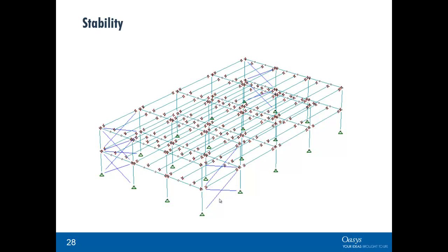Similarly, the steel frame as a whole: the real steel frame will have a concrete floor in there, which acts as a diaphragm. The model without that is maybe stable around the brace bays, but elsewhere from that, it's a bit wobbly. You need a rigid constraint on each floor level to make the structure work, and of course get the loads to the braces. We'll come back to this in a bit.